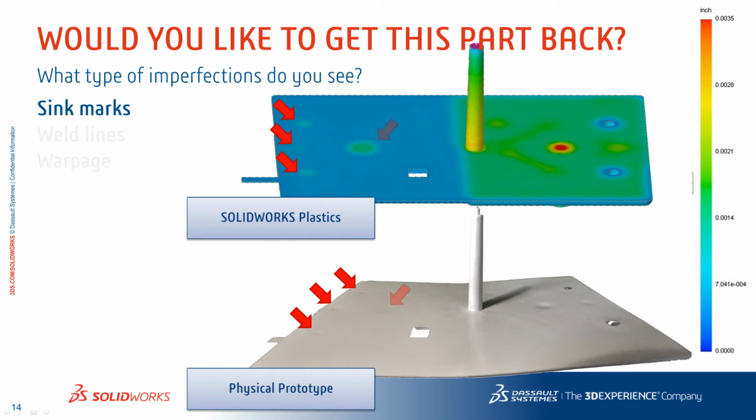The first defect that really stands out when I examine the physical part are the sink marks. And we're just talking a few thousandths of an inch, but with my well-polished, shiny mold surface here on the top, I can easily see the sink marks. What's great is SOLIDWORKS Plastics on the top predicted these exact same sink mark magnitudes and locations. So right away I can understand that this part is not going to come back very pretty.